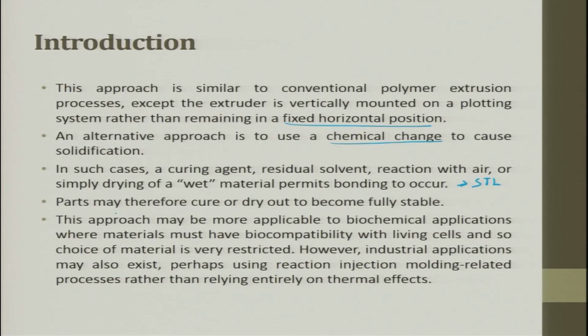Okay. Parts may therefore cure or dry out to become fully stable. This approach may be more applicable to biochemical applications where material must have a biocompatibility with living cell, and so choice of material is very restricted. This is more bio applications. However, industrial applications may also exist, perhaps using a reaction injection molding related process rather than relying entirely on a thermal effect. This is also possible. Reaction injection, we will see that in due course of time.